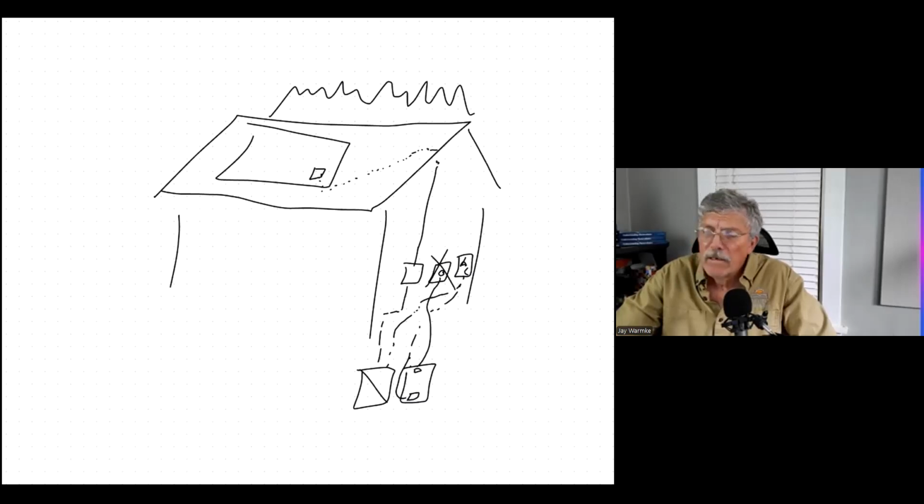Now, on your meter is a little label that says, warning, there's a second power source here. So that's required. And they look around within 10 feet. Oh, here's the AC disconnect. And it says solar array disconnect. So you disconnect, you turn that off. What did it just do? It turned off the power at the inverter. So now it's no longer generating power from the inverter.